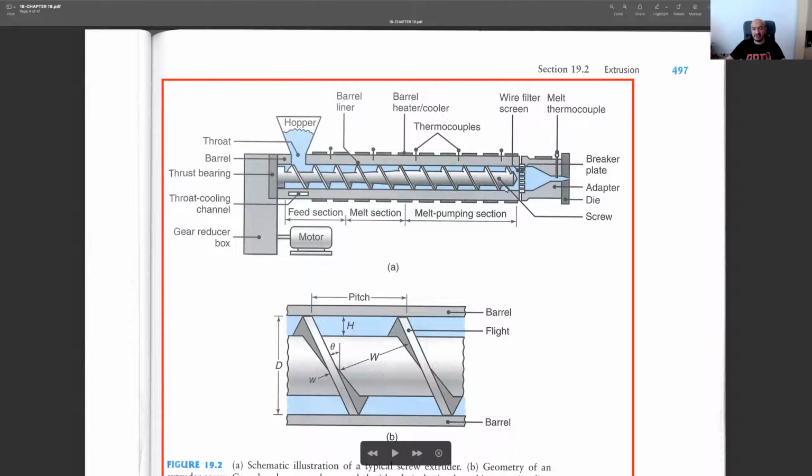So this is highly important. In the extrusion process, we make use of such a screw, a long one, maybe more than 1 meter sometimes. The screw has some specific parts. We have the feed section, where we are simply feeding raw material. Then we melt this raw material with the help of heaters here, trying to increase its temperature. The temperature also increases due to the friction between the particles and the friction between the walls and the particles. So for melting, we make use of friction and also the heaters.